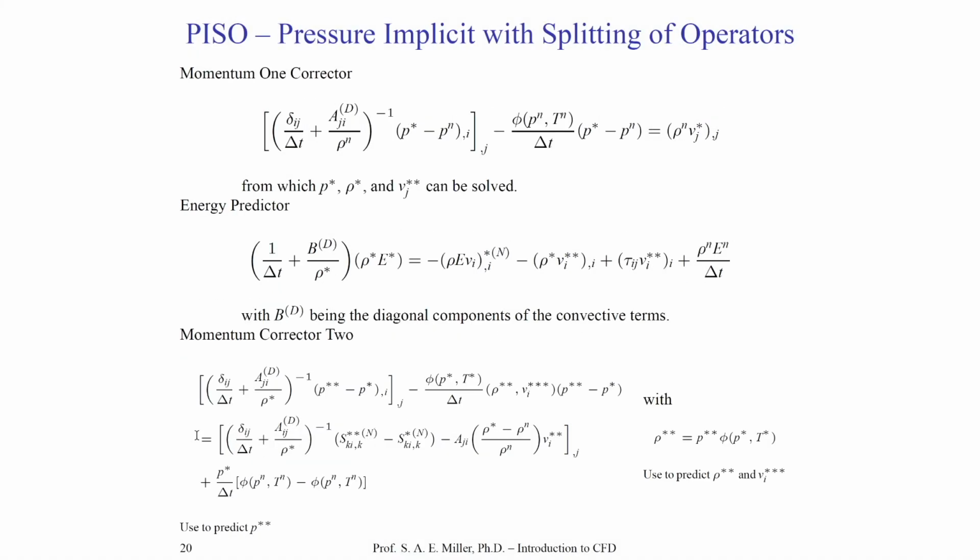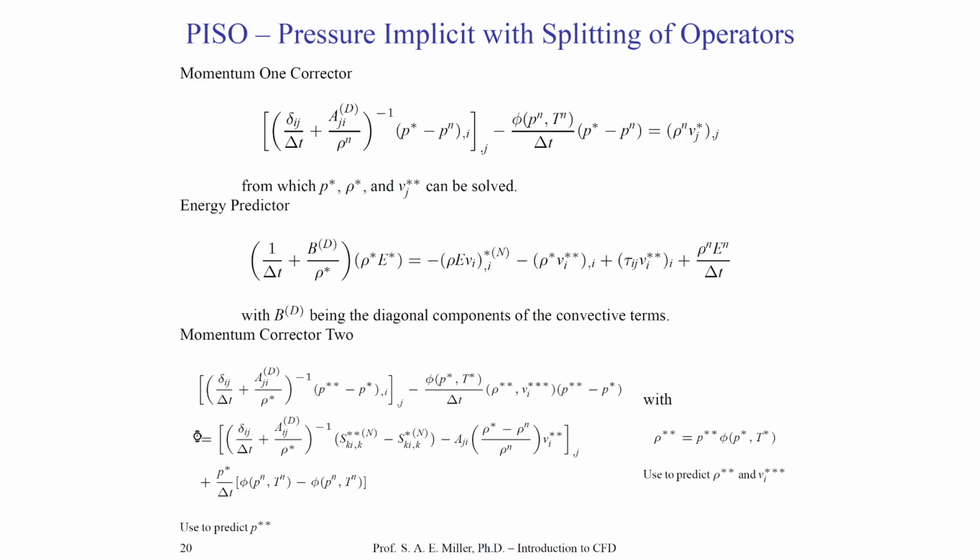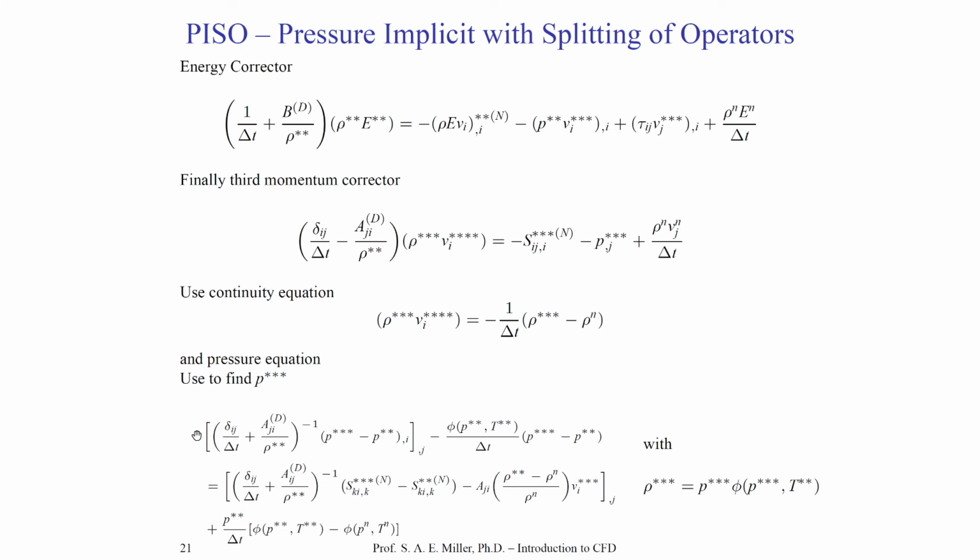These are all the equations that are used to find a 2- or 3-dimensional compressible flow solution of the Navier-Stokes equations with the pressure implicit splitting of operators method. So take a second just to review these equations. Because of time in the class, we don't have to review these in detail. But if you're curious and you're running PISO methods, you'll have to know that these are what are programmed and validated in most commercial solvers. It's very rare today to find research-based solvers that use the PISO method. We've looked at incompressible flows and some workhorse schemes implemented in most commercial solvers to find the solutions. And we just looked at those equations and gave you a very broad overview of the algorithm to solve them.